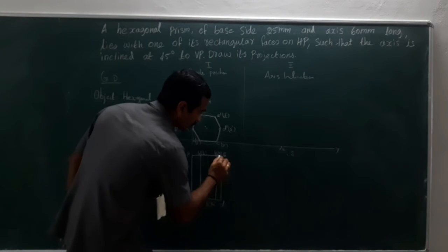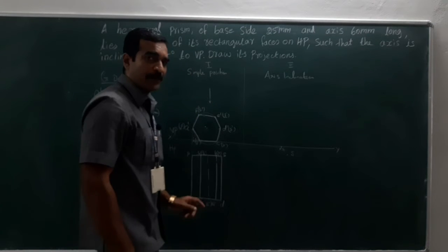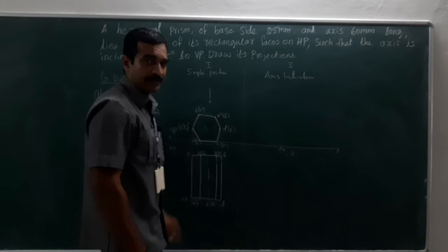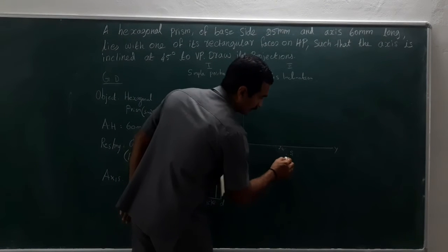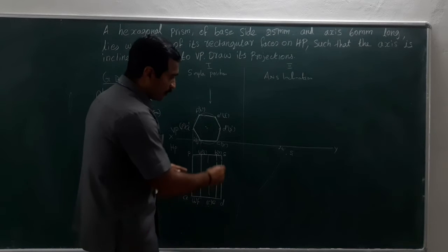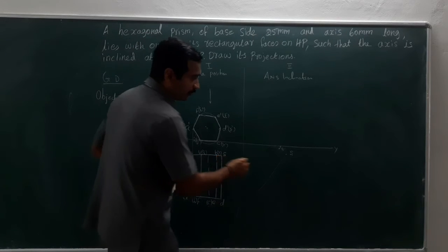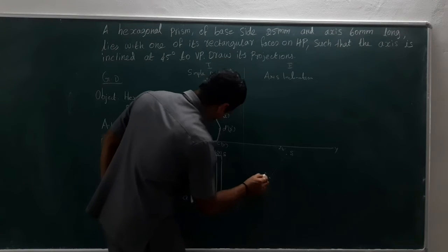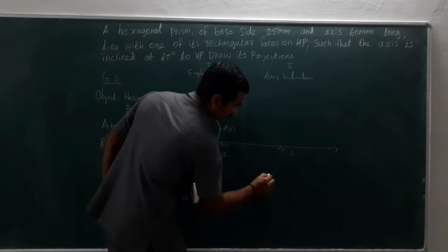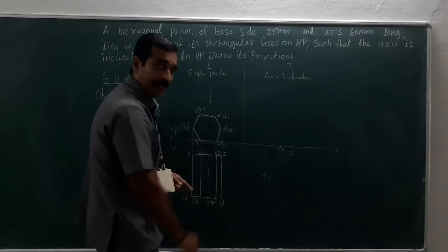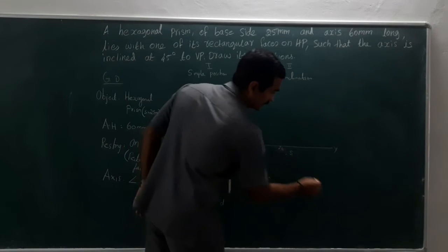Look here, this base is perpendicular to the longer edge. So keep the protractor in this manner and draw a 90 degree line. Now measure the distance between S and P in your compass, and cut an arc. This could be P1, isn't it? Now measure the distance between S and D in your compass, keep it at S and cut an arc.